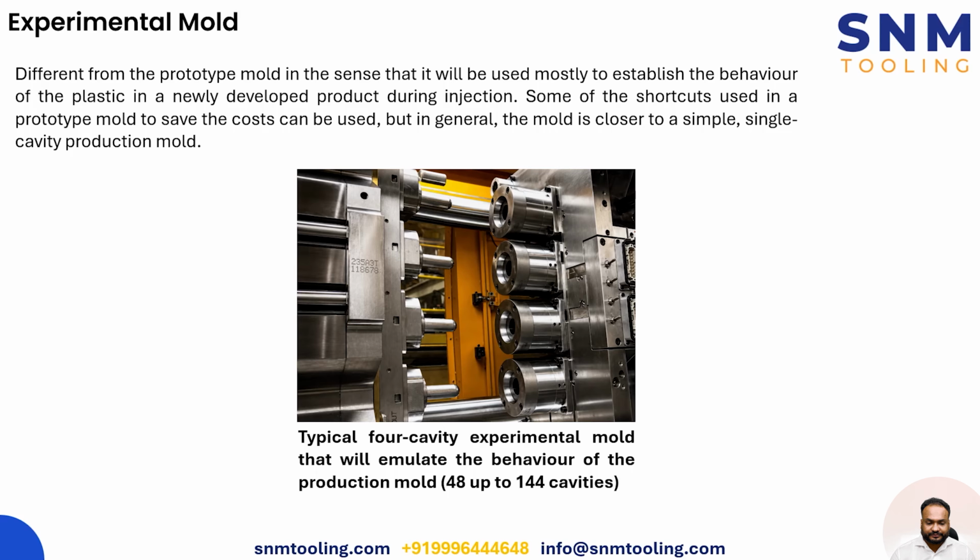So if you can see here, it's a four cavity experimental mold, right? Again, the behavior is something which will be emulated, right? The production mold, no matter how many cavities it has, the experimental mold would emulate or replicate how the production mold will behave. Although the experimental mold won't contain that many cavities, it would surely help in giving us valuable insights